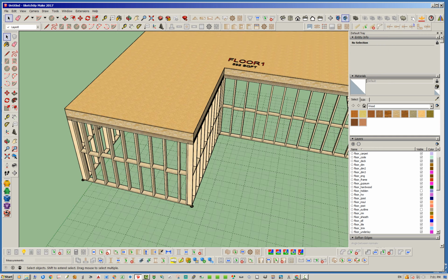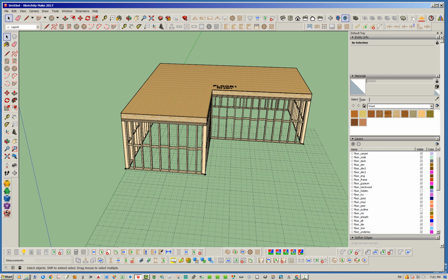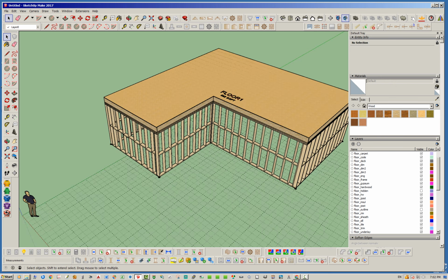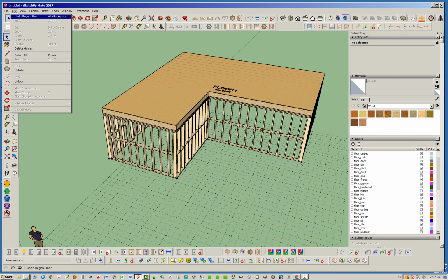Now that seems normal, but if, for instance, I raise these up and I raise this up at the same time, it's going to want to reconfigure this floor the amount that the walls have been raised up, but also raise it up the amount that it was translated, which sounds a little confusing, but basically you're double dipping it, and you don't want to do that. So if you're going to vertically raise the walls and you want the floor to follow, just raise the walls themselves. Or if you want to offset that floor vertically from where it would normally be located, then that's fine too. Anyways, it gets a little complicated, but I think if you play around with it a little bit, you'll figure it out. Okay, I'm going to just go back, put that right there for now.